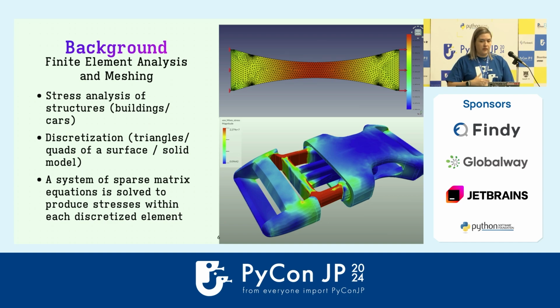In order to conduct this kind of analysis, you need to discretize a surface or a solid into a series of triangles or quads. These are examples of contour plots that basically say how close the material is to failure. And the essence of finite element analysis is basically solving a system of sparse matrix equations to produce these kinds of stresses at each point within the element.